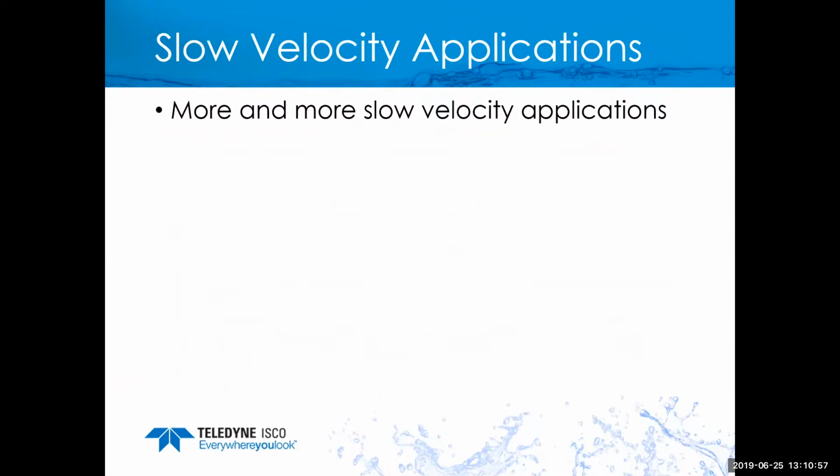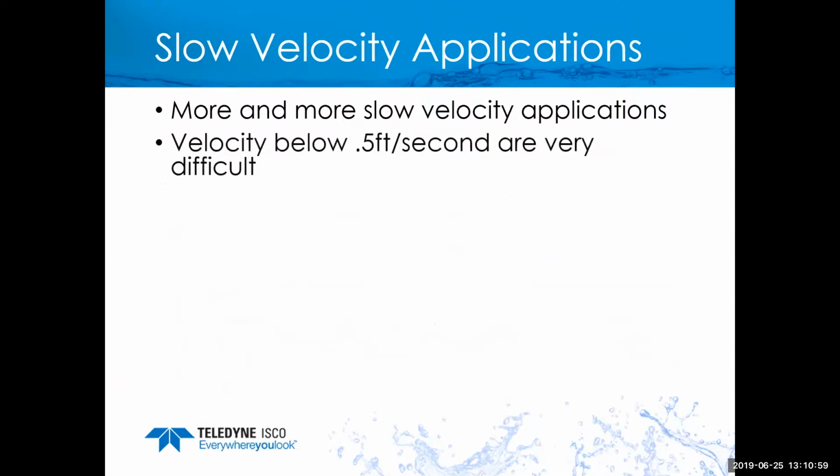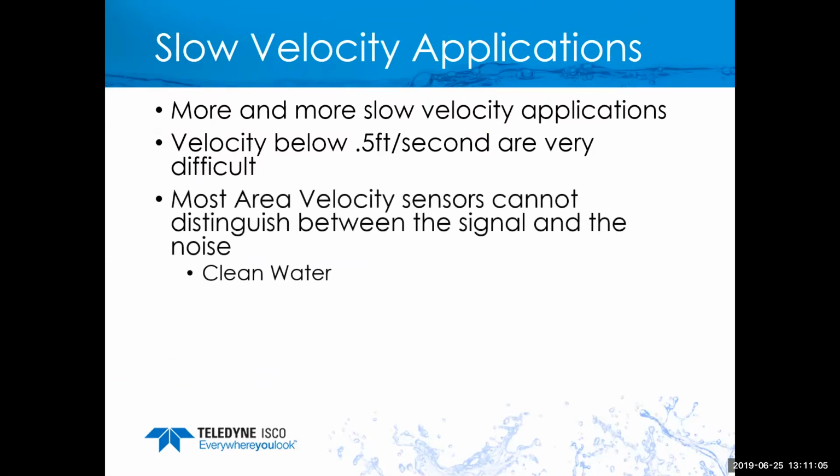Then we have a lot of slow velocity applications. More and more we're seeing those, and this is going to be difficult. Anytime you're below a 1/2 foot per second, you're going to be kind of at the low end of most technologies. Well, why can the laser work? It can because of the good signal to noise ratio.